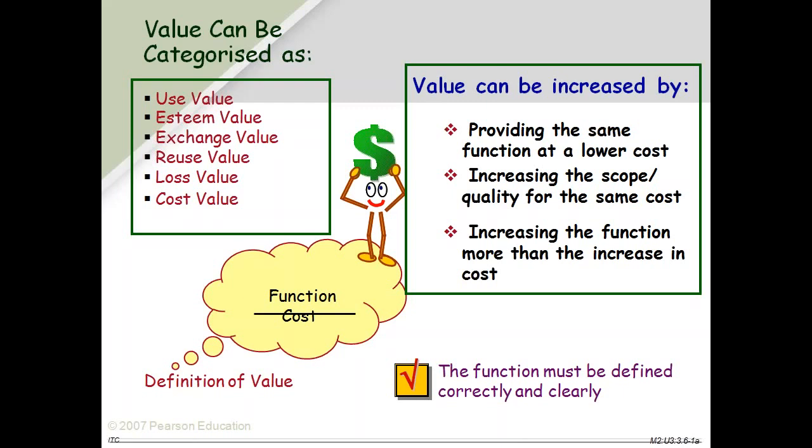The brass was being used because I need to chrome plate it. Then somebody came with a material, guys, instead of brass, why not use ABS, acrylonitrile butadiene styrene, which is a wonderful material that can be coated with chrome and looks the same finish. So when you look from far off as a customer, you don't see a difference. But for the manufacturer, the price goes down. That's what we call the VA part.